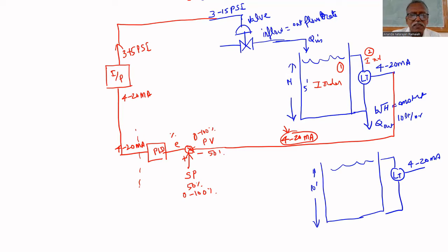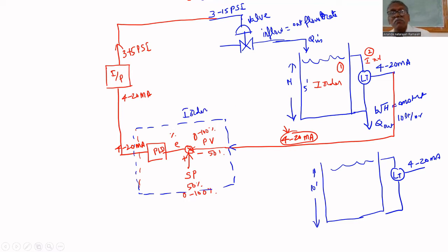But the level transmitter output is given to the PID controller. The PID controller has the summing block inside it. So in the PID controller, we give this process variable only. You can give the set point manually by number. So these two will be compared, and based on that, it will give output. Let us assume that is also another first order. It may be second order; maybe a second order PID controller. If you find the transfer function, it will be second order. But let us assume it is first order. We are using a P only controller, let us assume. Another first order. No system in the world is zero order. So minimum first order. So now the order of the system becomes 3, because all 3 are in series.